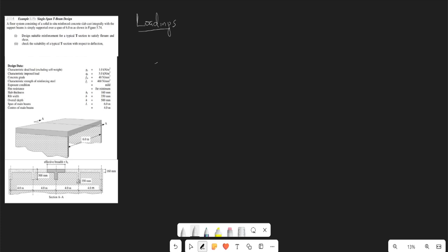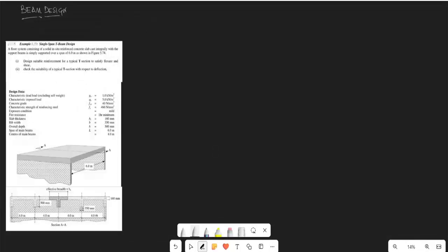All right, so to do that, many things come together to characterize your beam load, both for the dead and the live load. So let us just spell them out and go about all these things step after another. So the first thing we will do is to determine our slab loadings, because the beam is also going to pick up the load from the slab. All right, so to start with, we have our loadings, and it's going to be our slab loadings.